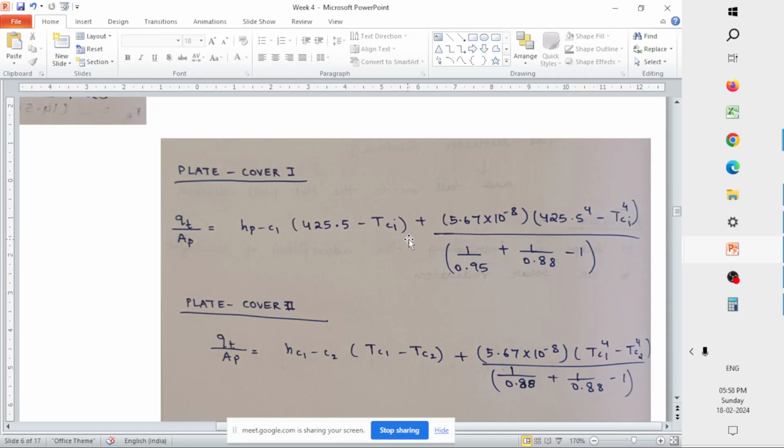The reason why it is black in color is because it will absorb all the radiation, all the wavelengths of radiation that falls on it, so that the temperature of your absorber plate will be high. As the temperature of your flat plate is high, if your delta T, that is the temperature difference between your absorber plate and your fluid, is very high, then the amount of heat transferred will be more, and it will only take a very less amount of time for the heat transfer to happen.